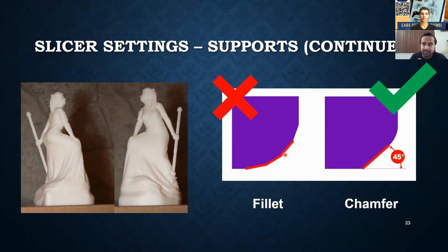And one more thing for CAD modeling purposes: you usually have the option to put rounds on your edges. We usually call them fillets or chamfers. Avoid fillets as much as possible, because this continuous curvature does not make for easy or nice layering, because it gets steeper and steeper and steeper as you go. The first layer is this, then the second layer goes all the way over here, then the third goes even further, and then it usually only stabilizes after you go above. So replace all fillets with chamfers. You'll just have better support structures in the long run.